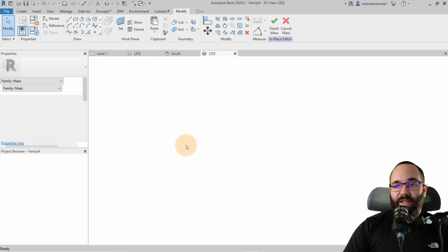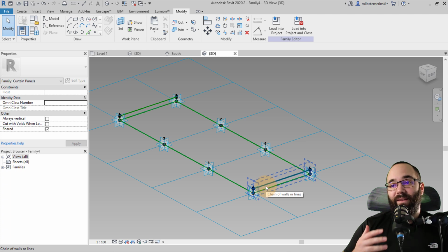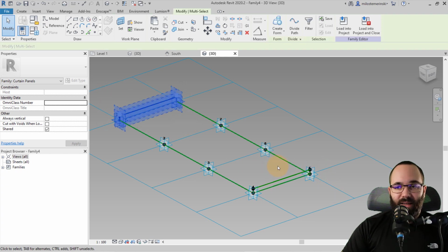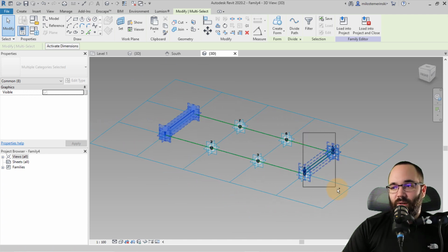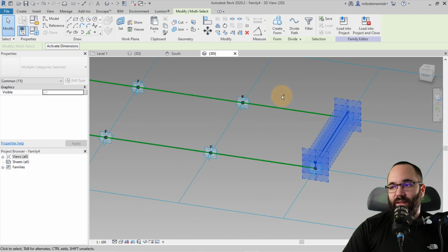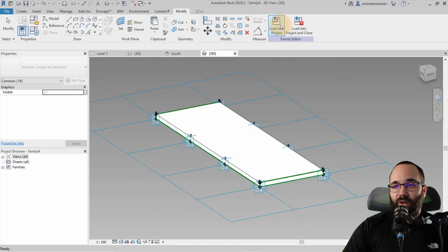So here, if we just connect these 2 sides, it's not going to be broken by the flexing of the points in the middle. It doesn't really care what the points in the middle do, because it's going to connect this side with this side here. So if I make a broad selection like this of these lines here, hold the Control key, make a broad selection of these lines here, just like that. Did I do a good job? Hopefully I did. And now I can go here to create form. Now it has a form that is those 2 sides connected.